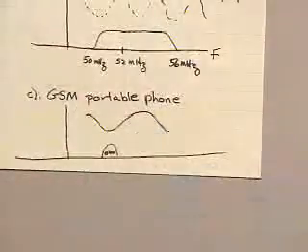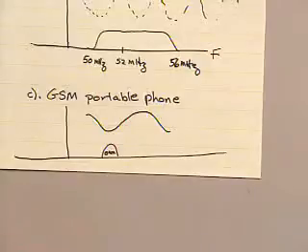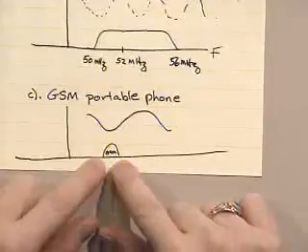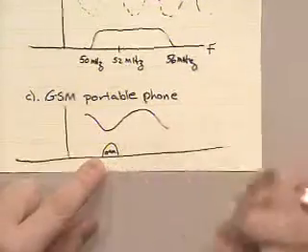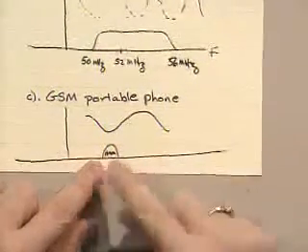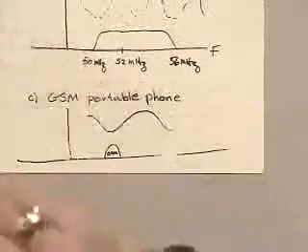The GSM was one step in this direction, which is originally the European network, but came into the United States. It uses QAM signals that are 270 kilohertz wide, rather than the original digital telephone system, which were only 30 kilohertz wide, and then they actually multiplex many users onto the same carrier frequency, and then your cell phone picks off your particular version. The wider you get, the more chances you have to have some good energy getting through the channel. Now, you're going to have to deal with the non-flatness in one way or another, but you deal with that.